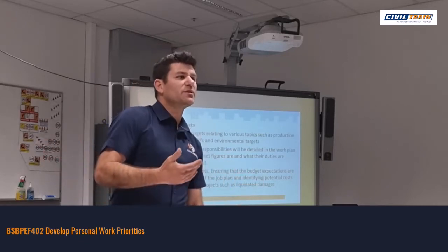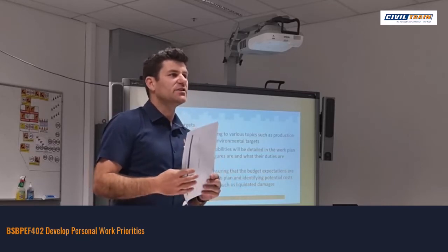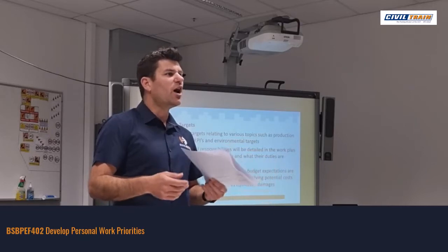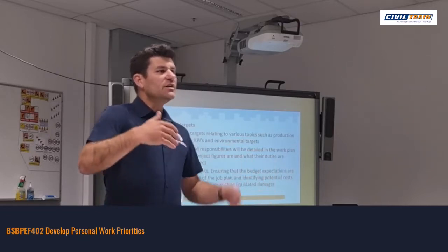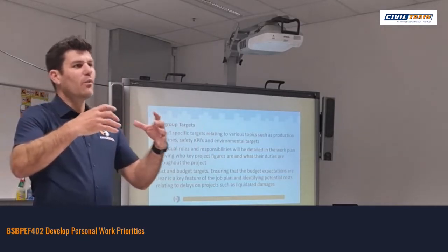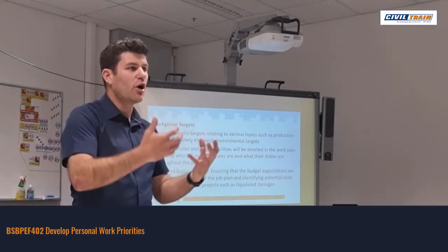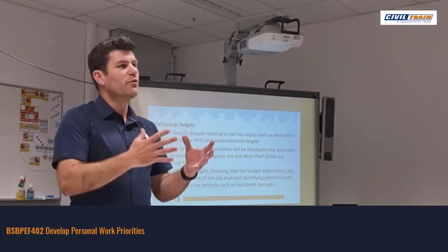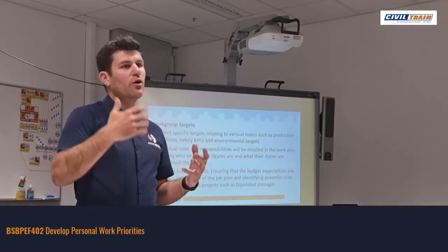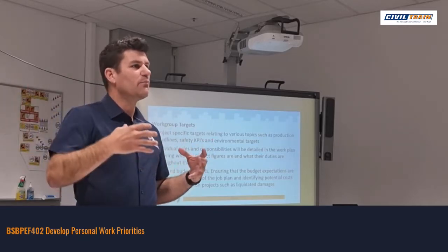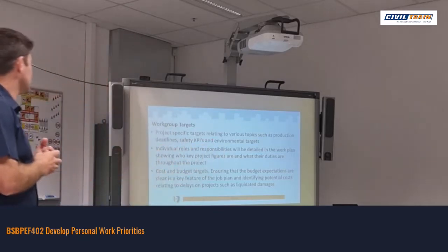What I would probably see in your work plan is that you would need to order your concrete probably 2 days prior, or I'd like to see that you're thinking about what's happening next. So in your personal work plan, we're going to get you to put in potential notes of how you would plan for that project. So the week before, we'd like to see notes of what's happening the following week to ensure that you are planning for those activities.